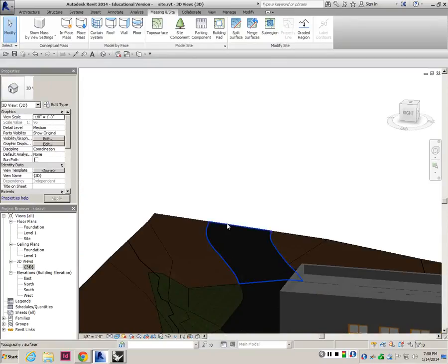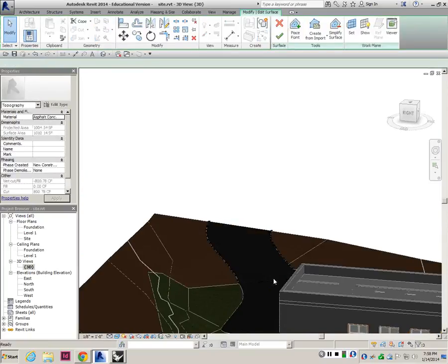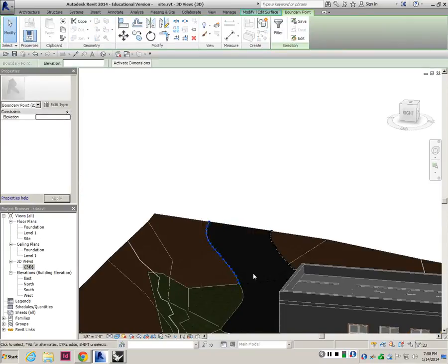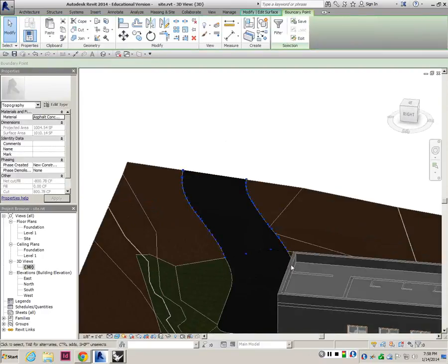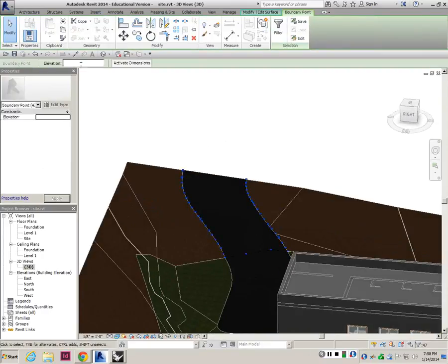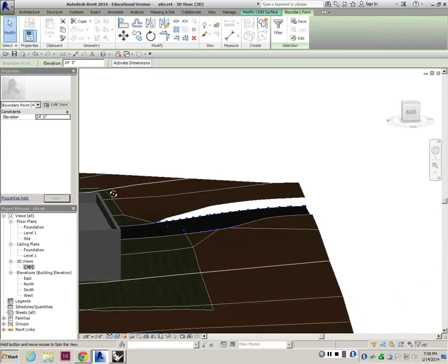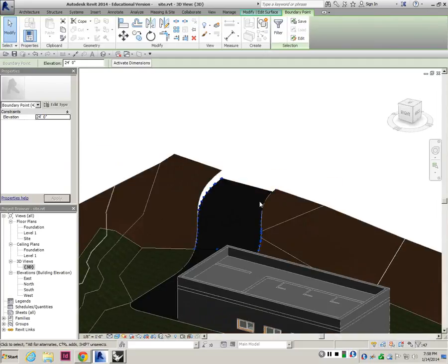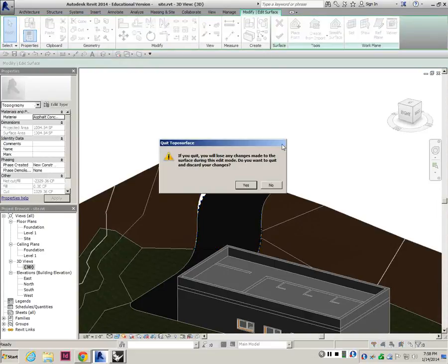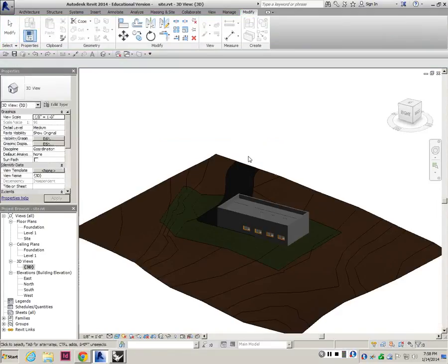You could also select this one and do edit surface, select all these points and give them a specific elevation if you want to fix them. In this case, it was 24, so I can select all these points and give them 24, and it will reduce the elevation of the road. Right? Then you have to do either the same thing to the side of the road, or to one side maybe. Okay. Let's keep it the way it is.